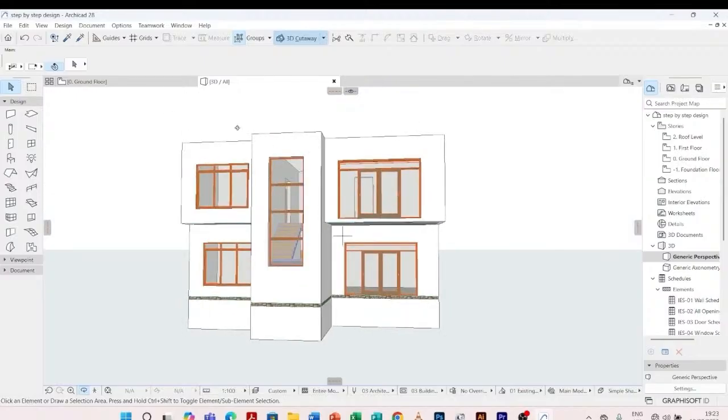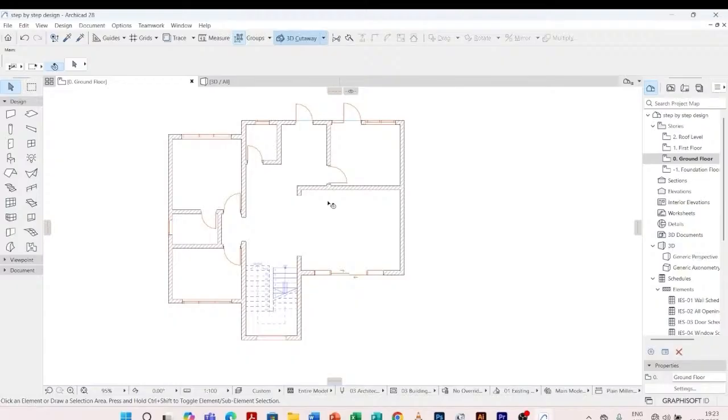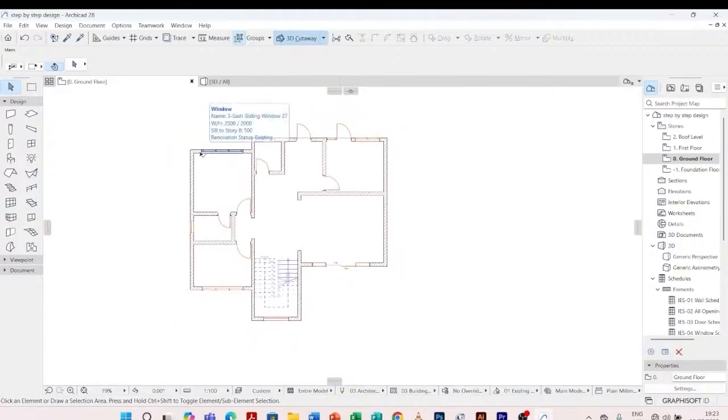Yeah, to start with, I'll open our ground floor. This is our ground floor. I'm going to have the veranda, the steps, and then the ramp besides our steps. So what I'm going to do, I'm going to first draw my lines. These lines are going to help me determine or to mark off where exactly I want my slab to be, where I want my steps to be, my ramp to be, and also give dimensions so that when I come to place the slabs, it will become very easy for us.